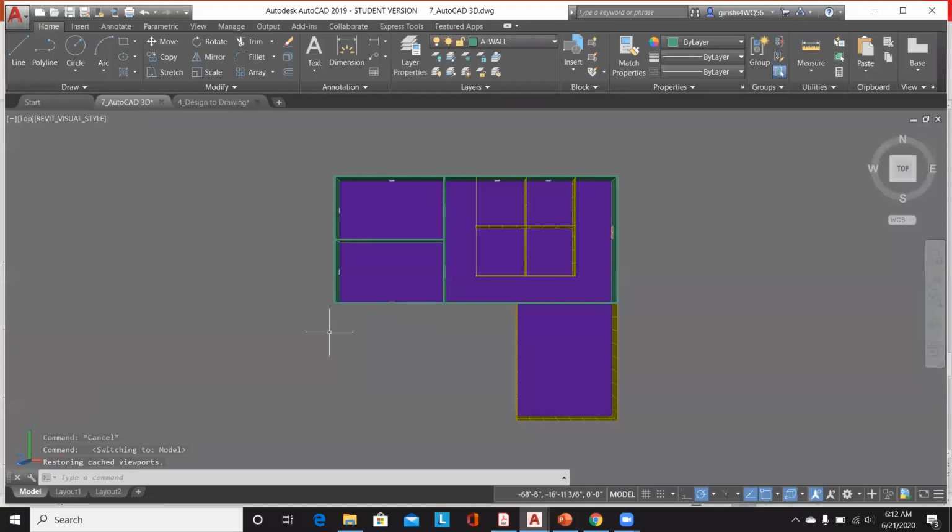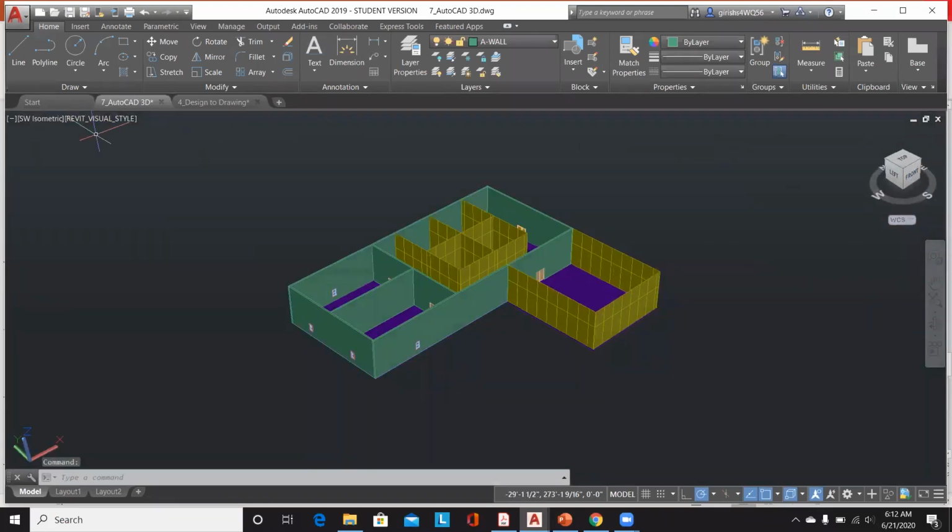So what happens is we need to define certain view properties. So when you select view cube and then you have the top left corner of AutoCAD, you have view controls. It provides access to certain standard views and the custom views that you have created in your AutoCAD workspace.